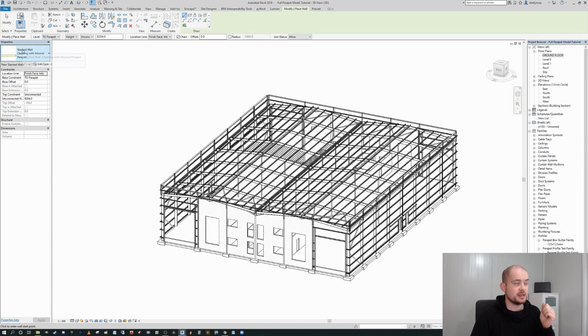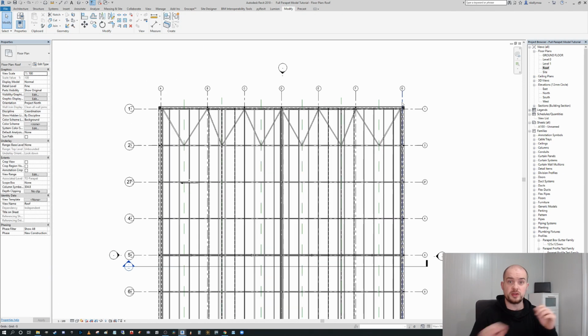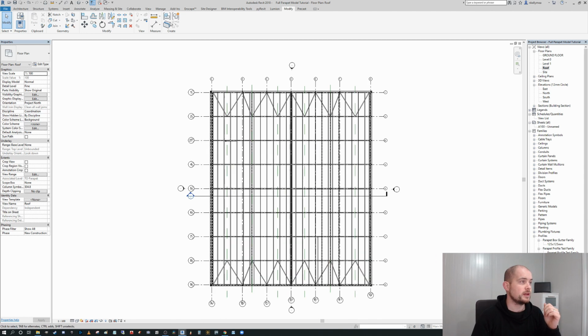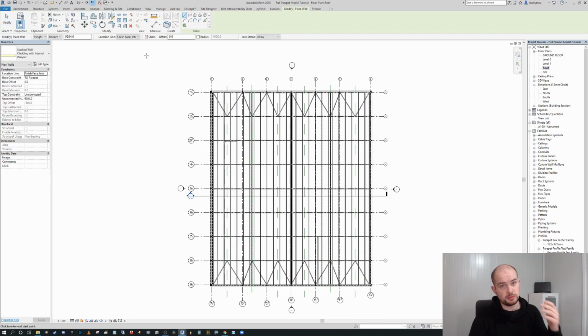And under here you can see, in order to check it, on the properties on the left hand side, you can see it's called up a stacked wall, okay? So going to our roof plan, okay? We want to draw this stacked wall around the boundary of the building, okay? So going to architecture, wall, okay, or just pressing WA on the keyboard, we have our stacked wall selected,